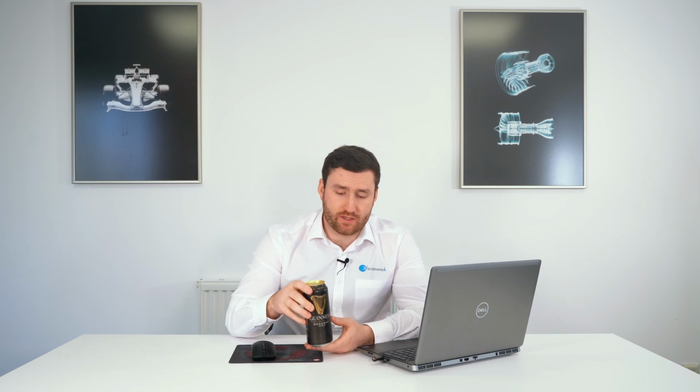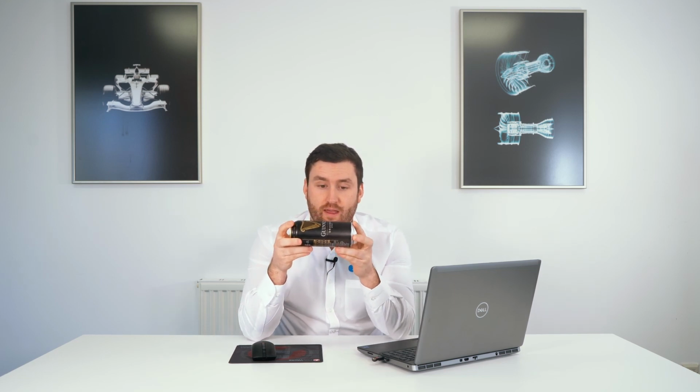Okay, so we've scanned our can using real-time quality meshing. First of all, I scanned it in the upright position like this, and I also scanned it a second time in a horizontal position, trying to get as much data as possible so that I can align those two bits of data using a best fit data to data object alignment. Once that data was aligned, I then cleaned it up and meshed it together to create a single polygonal model.